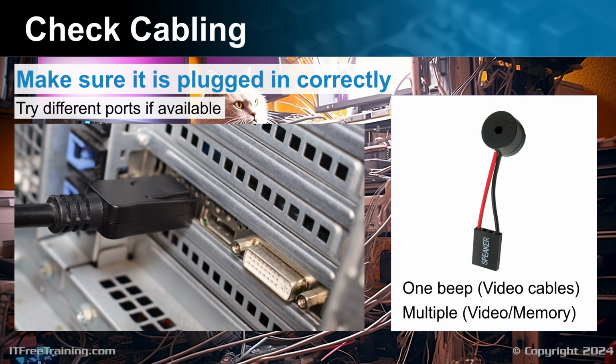If you have a black screen, the problem is most likely something to do with the monitor, the cabling, or the port on the computer. It is possible that it is the video card. However, if a detectable problem with the video card is found, you will generally hear a series of beeps which may sound something like this.